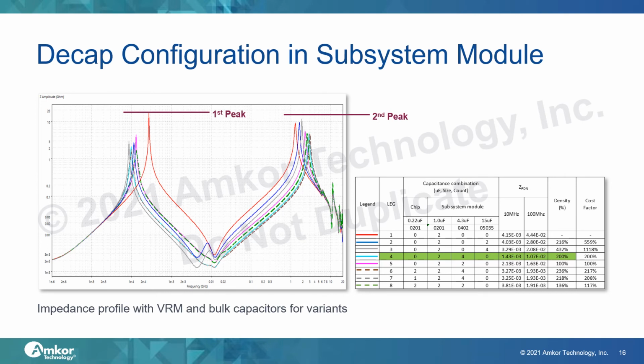The subsystem module can achieve low mounted and spreading inductance due to a tight gap between component and die and thin dielectric. Another factor to reduce impedance peak is to take advantage of an MLCC with higher ESR in order to damp some of the parallel resonance and manage the impedance peak. Unlike motherboard, mounting inductance in this case is relatively low, so ESR could provide an optimum capacitor value.